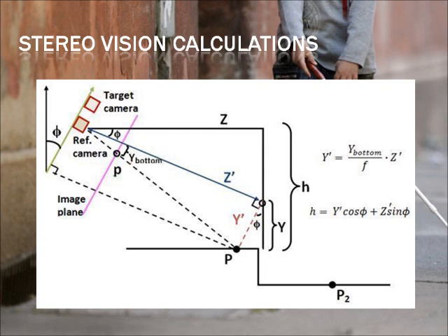This allows us to detect drop-offs at closer distances, but also comes at a cost of more complex calculations. As shown above, x is now y prime, and z is now z prime. By utilizing our tilt angle, we can calculate the depth/height of the edge in question, relative to the bottom camera. By running this calculation on successive edges, we can find the height difference between them, the depth. For each frame, 5 sets of successive edges are checked.